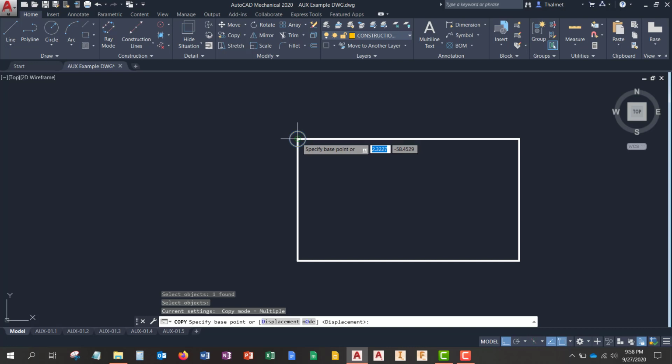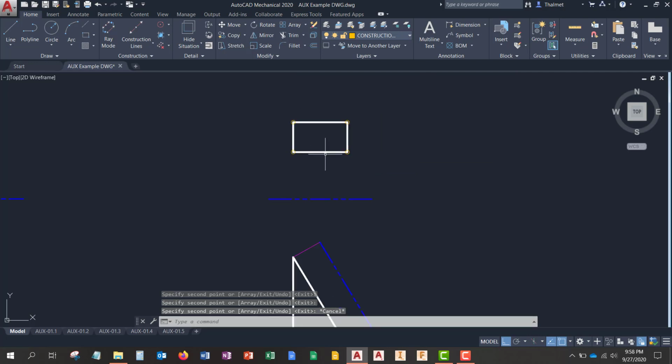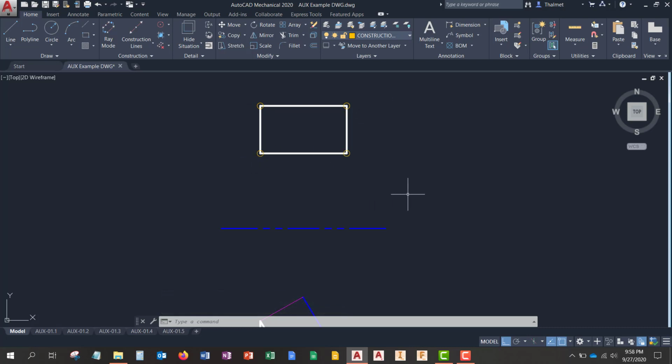So essentially, whenever I'm looking at my inclined surface that I want to make an auxiliary for, I want to make sure that I'm aware of every single point on that surface. That's what my little reference construction circles here are representing. I have 4 points on this particular plane, and pretty easy to tell just by looking at it.